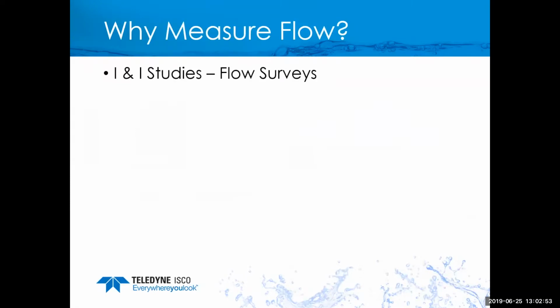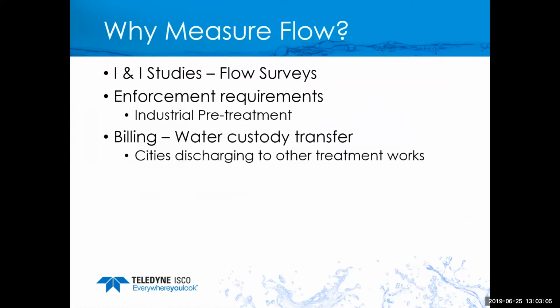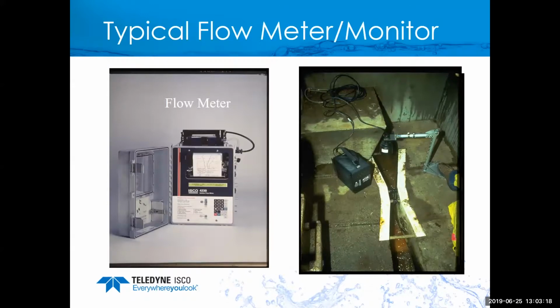And so I'll just keep on going. Why are we measuring flow? I&I studies, or flow surveys as they call them in the UK, enforcement, industrial pre-treatment, billing, water custody transfer, which is a city discharging to another treatment facility. You see that in places like Atlanta, Phoenix, Milwaukee, Boston, Denver, and so on. So a lot of places out there do that.